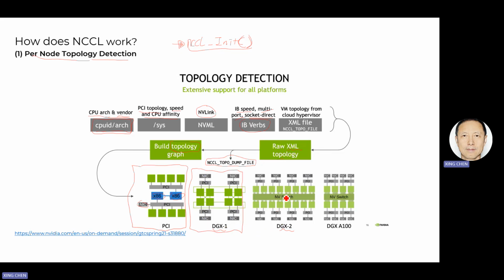And then furthermore, we have these DGX2 systems. Here we have 16 GPUs, and these 16 GPUs are connected by the NVLink switch. And then two GPUs are sharing one PCI switch, and the switch is also connected to a NIC. Supposedly it's the InfiniBand NIC. Okay, this is the most common case for the moment.